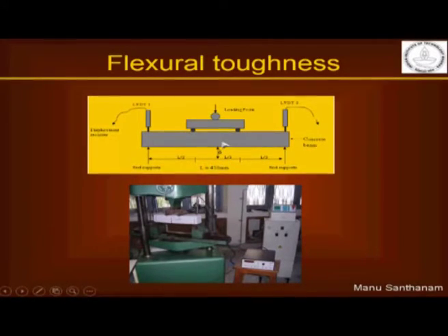We also altered the setup in such a way that we could measure the displacement which may be happening at the supports also, so that we actually get the net displacement at the center and use that for our calculations. You can expect the supports may also slip and have some displacements. So we measure those displacements also and subtract those from the actual displacement that the specimen undergoes right in the center, right under the load.